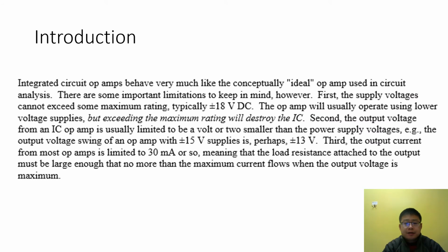And there are some important limitations to keep in mind. First of all, the supply voltage cannot exceed the maximum rating. And also the current cannot exceed the maximum rating. Usually it's 30 milliamperes, so be careful when you use the circuit.